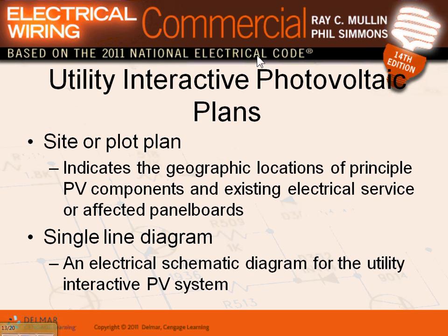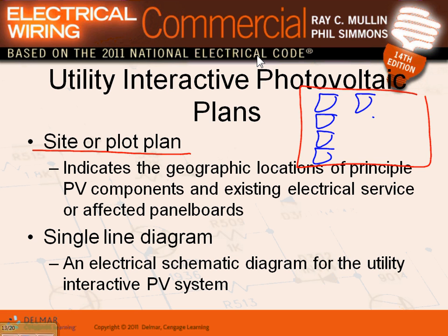Okay, a couple of other things, guys, that we have here is the site. When you design a system like this, obviously you have to have the site plan or plot plan like we did. In ours we showed the parking lot fixture. We have to show the location of all these solar systems. So here's my site, and I'm going to plant all my modules this way. Here's string 1, here's string 2, or array 1, array 2, and this is the plan I'm going to be doing. So you have to have some type of a site or plot plan, PV components and existing electrical systems.